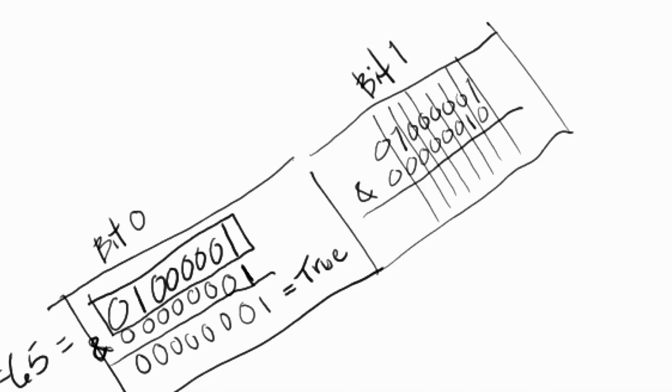So we can do the bitwise operation, and we know that 1 AND 0 is equal to 0. So that is a correct determination of this second bit. It is a 0. 0 AND 0 is 0, and 1 AND 0 is a 0. So now this is equal to false. So in this case, this particular bit and pin will not be lit up. It will not make the LED shine.